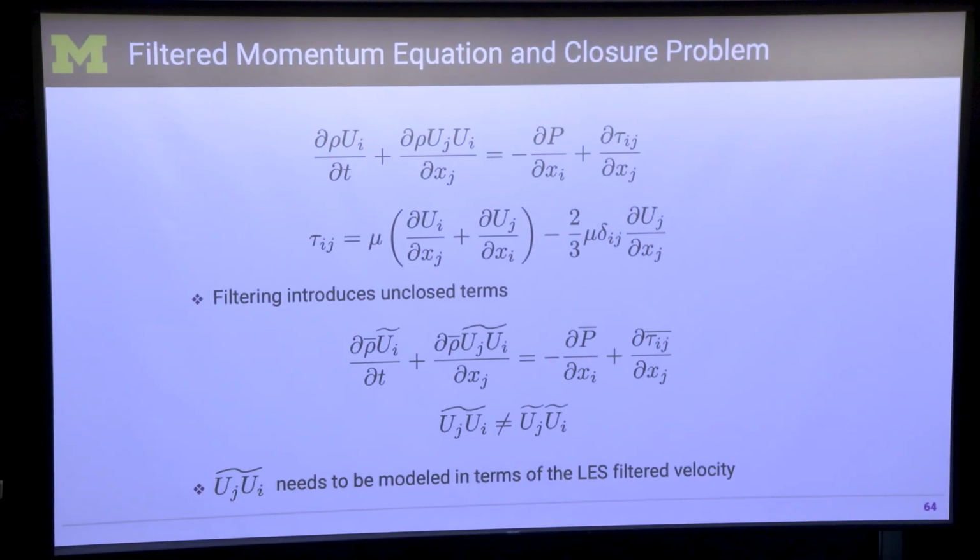So momentum, it's three-dimensional. All turbulence is three-dimensional. No LES should be two-dimensional. So whatever else you learned from this course, do not do two-dimensional LES calculations. So LES is three-dimensional. And ui tilde is the equation for the ith component of velocity. The three components, we live in a three-dimensional space, so it's u1, u2, and u3, right?